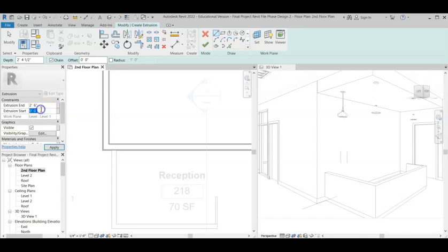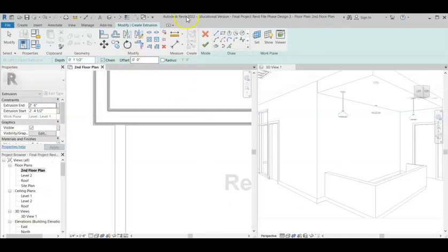The extrusion start will be at the top of the wall. So that's 28.5 inches. And there's a difference of 1.5 inches, so that will give us a 1.5 inch worktop. So I'll start by drawing that line 1 inch out. And then I'm going to use the pick line tool. Set my offset at 1 inch.